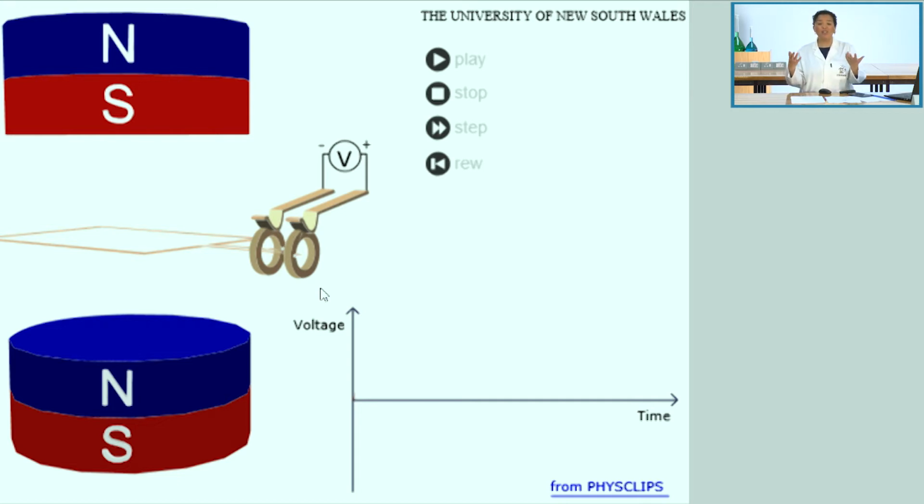The wedding rings association is just a tip for you to recall the actual physics content in a test or an exam. But yes, you're right, we do see two little slip rings over there, and the mere fact that I've got two slip rings tells me we're dealing with AC. Is this a generator? Yes, because I do not have a power source, but I have a voltmeter which would read an induced EMF. Then furthermore, I've got my armature or my coil, and it's placed in a magnetic field. We're going to rotate that coil, and the mere fact that we've got a coil being rotated or mechanically moved in a magnetic field will induce an EMF.